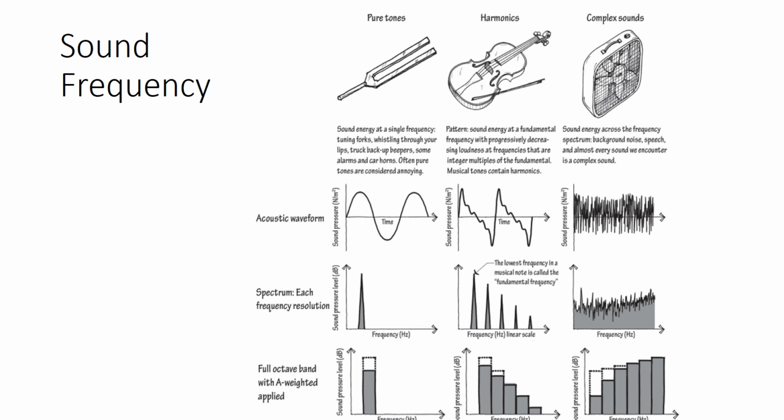So it will be a band, and we have to keep that in mind, because we have to design buildings according to the sound source we are dealing with. Accordingly we have to choose the design and the materials also, because multiple materials have noise reduction capacity at different frequencies.